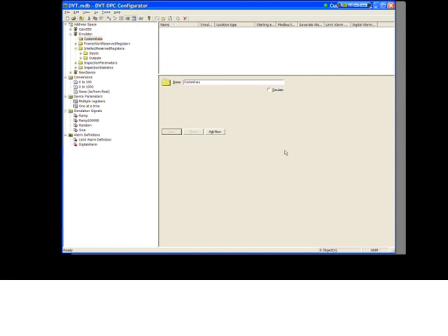It takes a while for those changes to take effect, or maybe they just take effect after you restart your monitor view or any other client that is connected to the DVT OPC server. So I generally have all clients disconnected, make my changes, and then bring up the monitor view to test and troubleshoot and make sure everything's working, then shut that down, and then open any other OPC client I want to make a connection to.